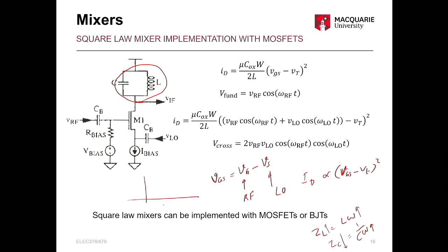So this would look like this. That's the part of high pass and a part of low pass. Do you see the low pass here? Sorry, this is the high pass part, and this is the low pass part. When you combine them, you get a band pass here, the shaded part.